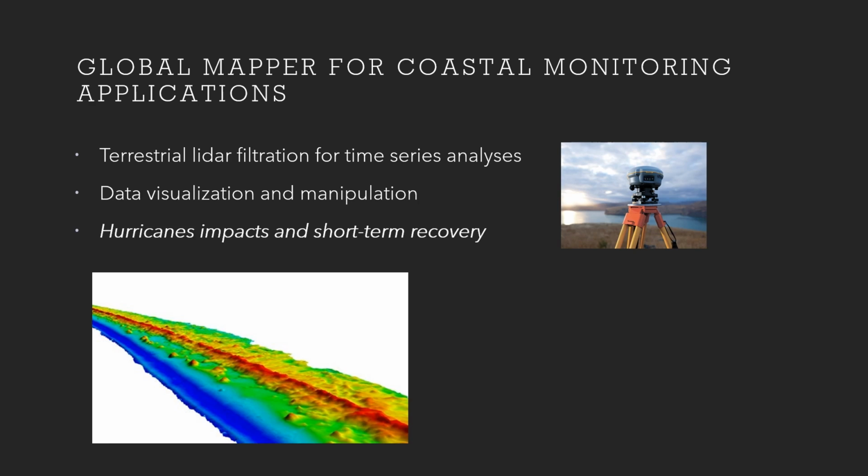And it's an easy way for me to use the LiDAR module, import that, and filter it as needed to further conduct analyses, as well as data visualization and manipulation. So oftentimes with elevation models, I'll see that there's a strong vertical bias. So that allows me to easily correct that if I need to.